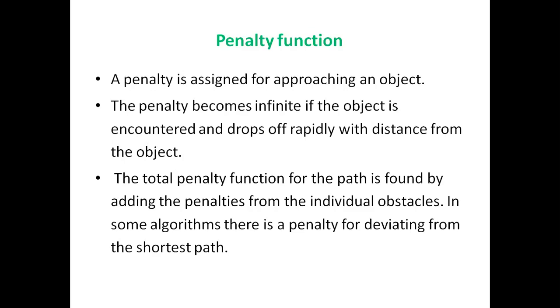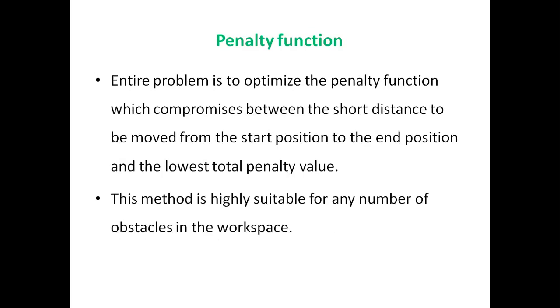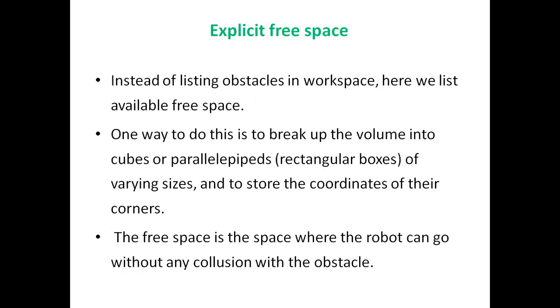In some algorithms, there is a penalty for deviating from the shortest path. The entire problem will be to optimize the penalty function, which compromises between the short distance to be moved from the start position to the end position and the lowest total penalty value. So this method is highly suitable for any number of obstacles in the workspace.